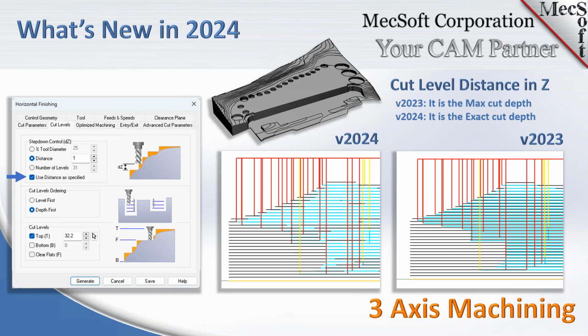Some users didn't want the system to change that distance at all. They wanted these cut levels to be exactly as they specified. And in the 2024 version, you can do that, but the problem with that, obviously, is you will not get a cut level at the bottommost cut. So, that's the trade-off here. But in some situations, the exact cut levels are important to customers, so that's why we added this enhancement.